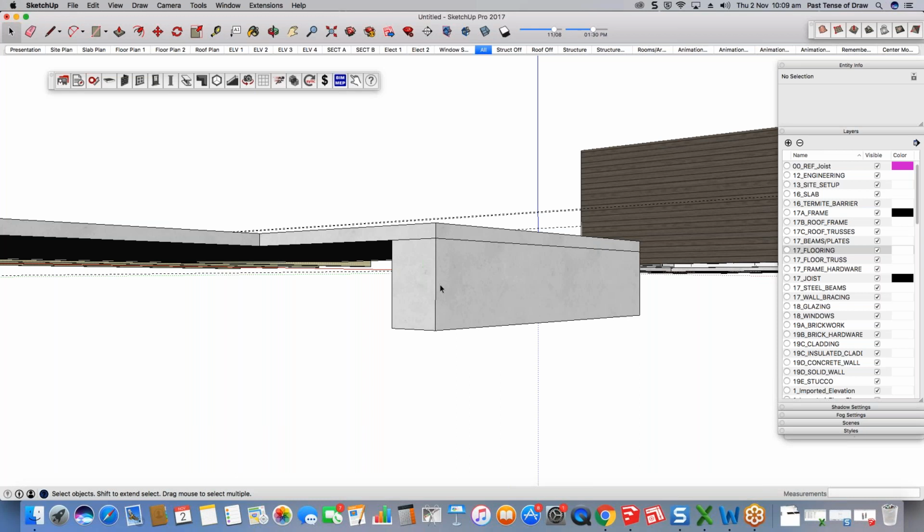Now what you can do is dim it. So going into the PlusSpec dim tool, you can do this around the entire perimeter, whatever you want to do. Put it on the layer, so the concrete or the footing layer that you want. So you just need to obviously understand those, give it information, naming, etc. And then just to finish the job, all you want to do is copy the concrete, so you want the footing texture. So you're going to go into your bucket tool, find the footing concrete, and just paste it on. Now it will be quantified.